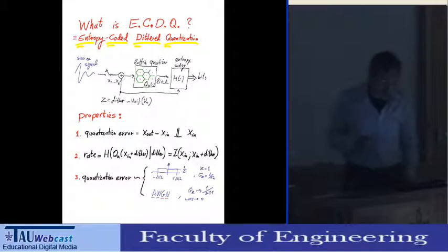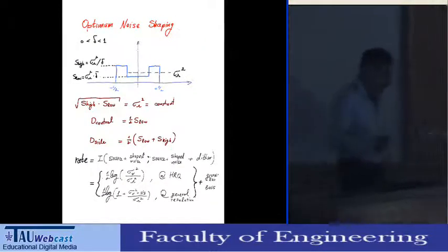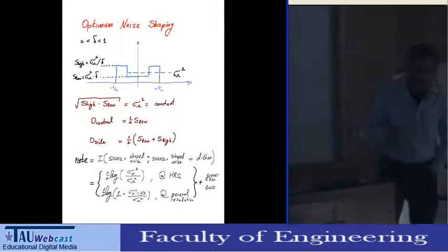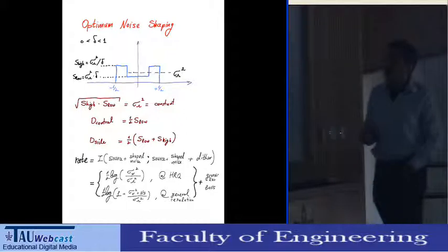And this allows me to close the gap I showed before, the quarter of a bit, which is the penalty for using scalar quantization. But anyway, the ECDQ is not so important here. It's just important to understand that the noise is really additive when I use dithered quantization.